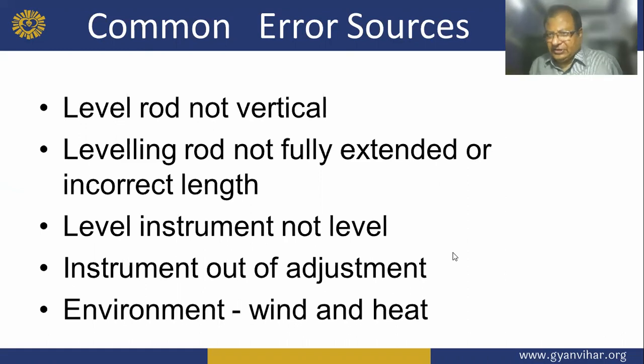Level rod not vertical: if a person is standing with the rod, it may be like this, but he is like this. It is a common error. Leveling rod not fully extended: it is open up to this area and open up to this, which is incorrect.